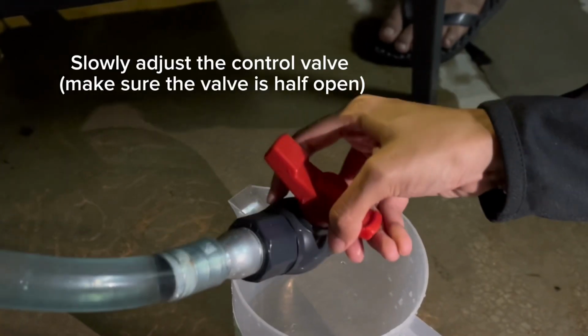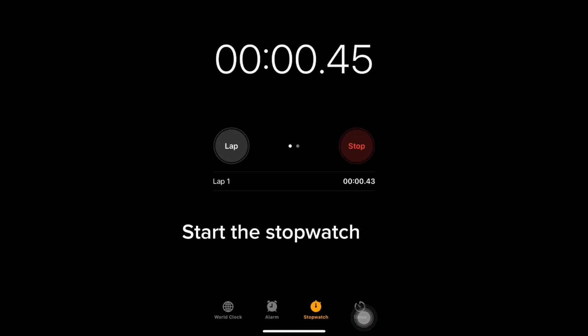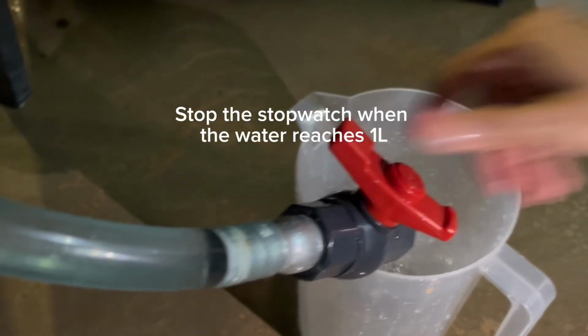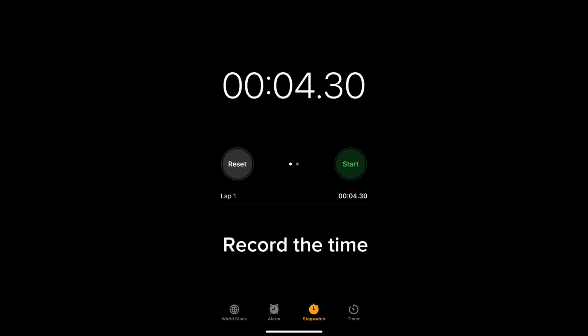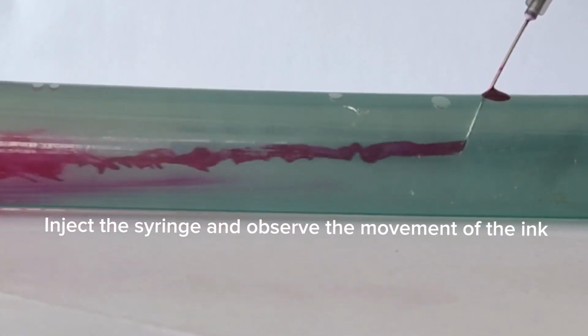First, slowly adjust the control valve and make sure the valve is half open. Then, start the stopwatch. Stop the stopwatch when the water reaches 1 liter. Record the time. Then, inject the syringe and observe the movement of the ink.